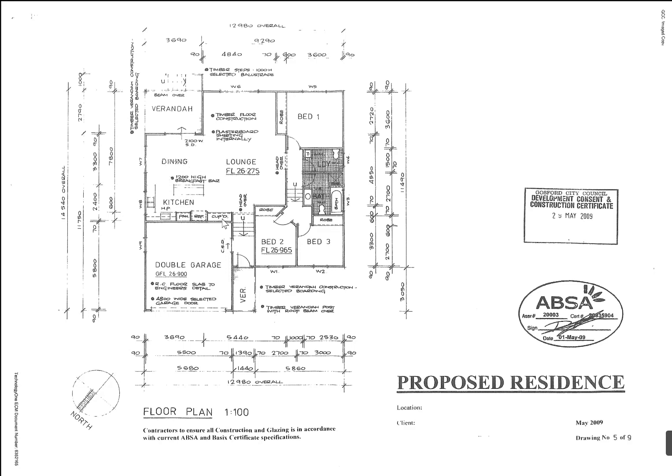In the kitchen area here, we've got a cupboard, a refrigerator, a small pantry, a hot plate, a sink looking out through a window, and we've got a breakfast bar here. We've been given the information of how long this return is because we've got a dimension there of 2400 from the internal walls. That's how long that is. But we don't know the width of this gap here to this island. We don't really know the dimensions of the island either. So there's information missing in this drawing.